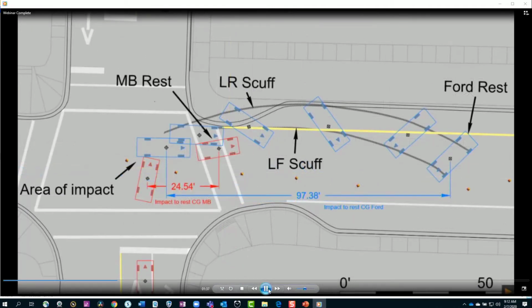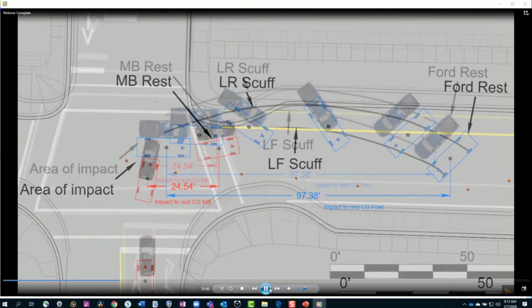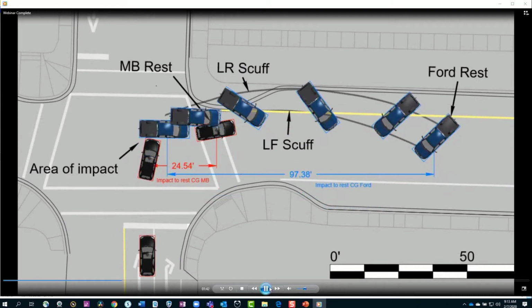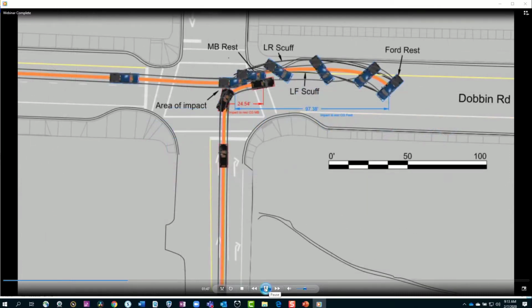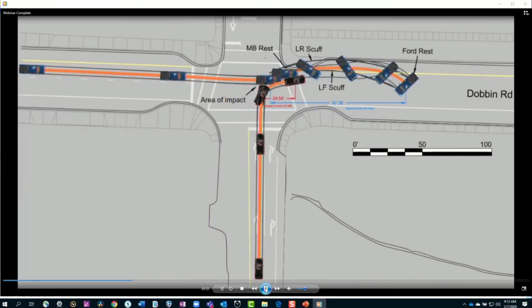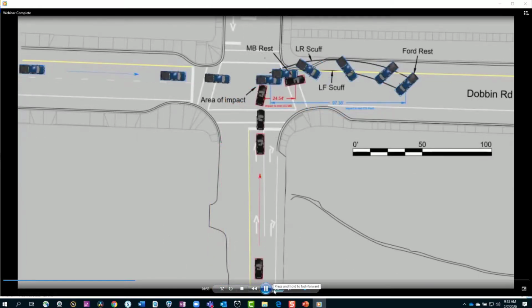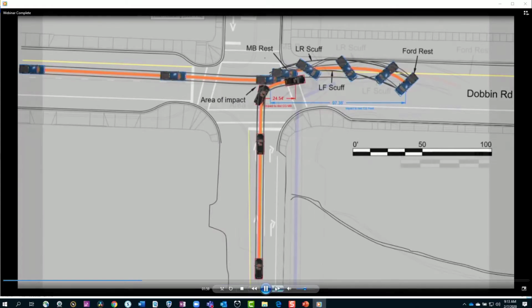But I said we were going to create an animation. So here's how that happens. I now go to the 3D vehicle library. I take the exact same 3D symbol, place it on the 2D vehicle, which we've already shown you is on its marks. And now I'm going to incorporate a tool called Animate from Stationary Points. I simply select the symbols, let the software do the work, and look at this animation that's created from simply one click.